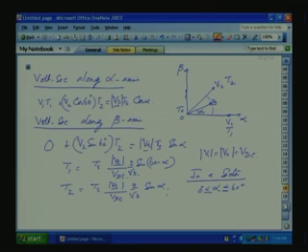T0 is equal to Ts minus (T1 plus T2). So for the rest of the period, the T0 period, we will switch the 0 state. Now, as we go from 0 to V1 to V2, that means inverter switchings are there.